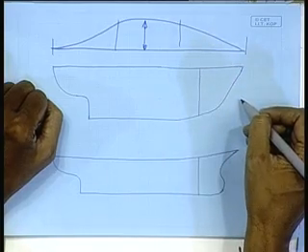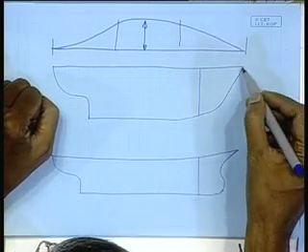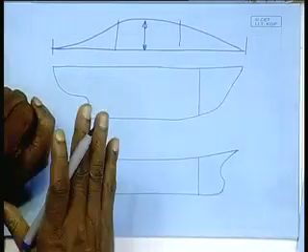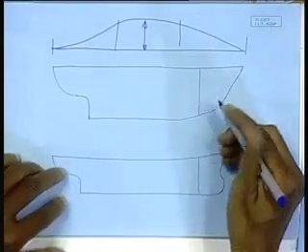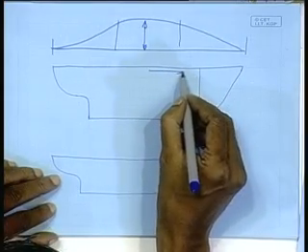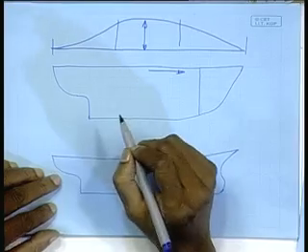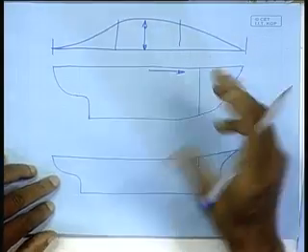So, the load coming due to the bending moment, or the stresses generating due to bending moment in the forward end, is gradually going down, it is lower. So, in the process, as we move from the center to the forward, we will see that there is a gradual reduction in plate thickness, gradual reduction in the scantlings of the stiffeners, right.